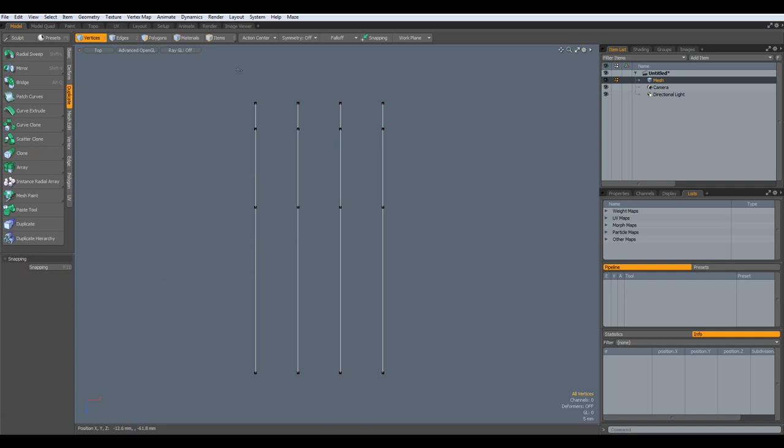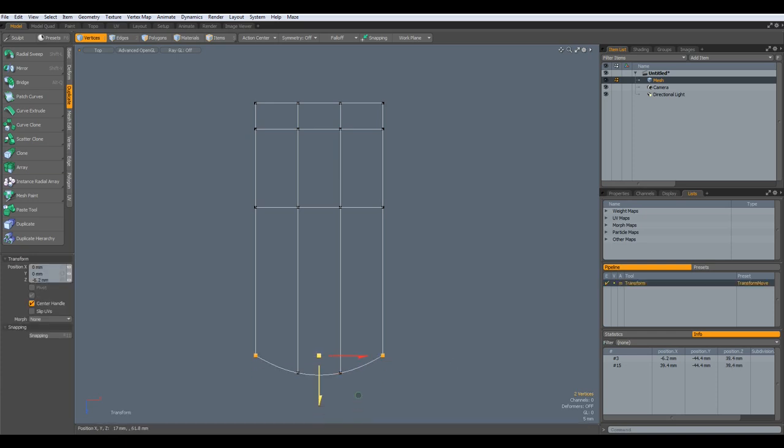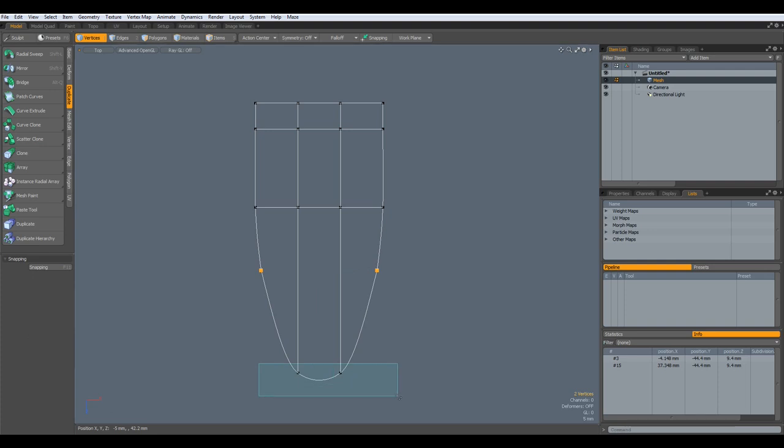and go to vertex mode, select these verts, the P key, do the same here, P, P, P key, and now we can start tweaking these vertices here, W key, to about here, R key, maybe this is too big, make it a bit shorter.